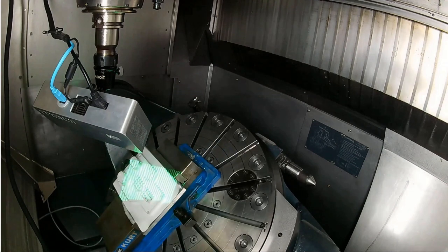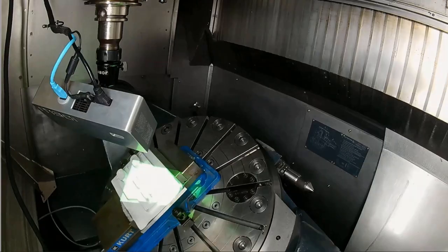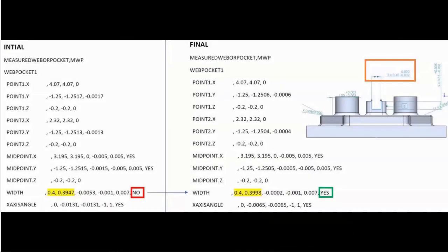So I call this intermittent because you have to stop the process to get the scanner in there to be able to capture the scans, run the deviation analysis, and then you can continue from there. But what if you run into a scenario where you can't fix it, right? If you cut too much, or for example, you're not going to be able to detect tool breakages right in the middle of machining. So it's a bit of an intermittent way of doing process control.